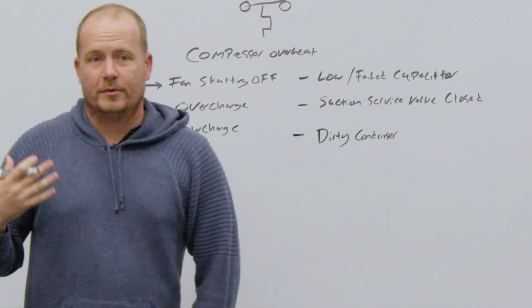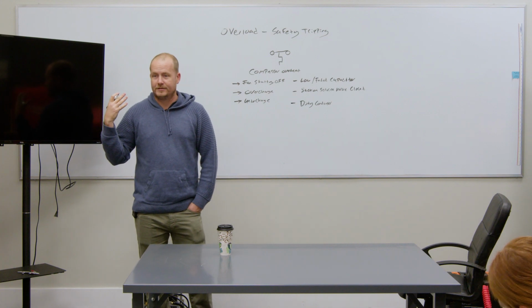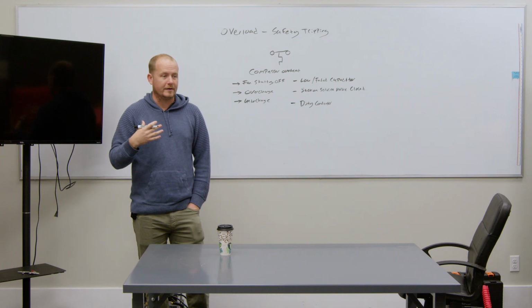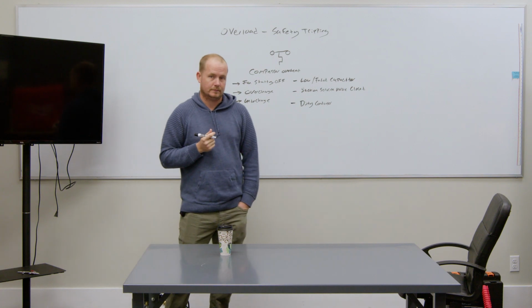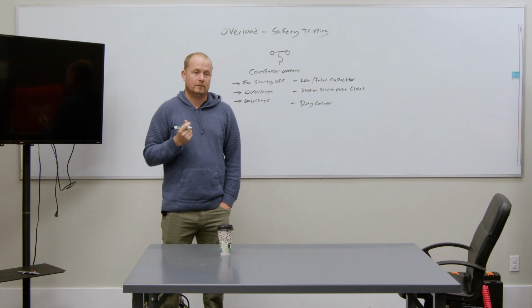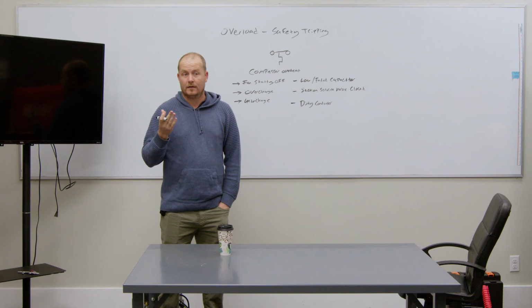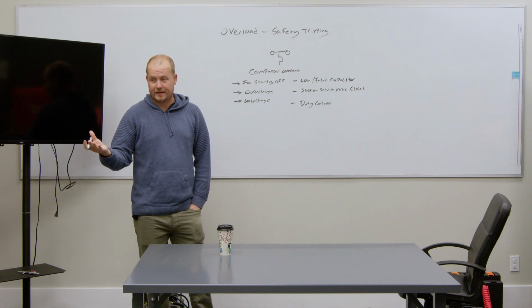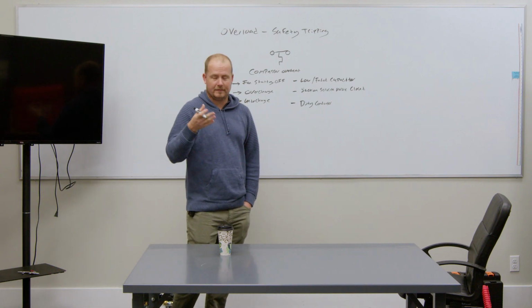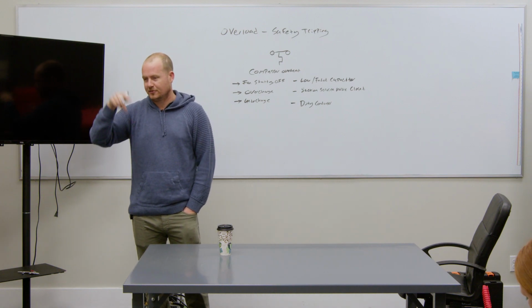So if you run into a compressor that is going out on thermal overload, what are you going to find? What is it going to be doing? Well, what will be off? Hold on, what will be off? The fan will be running, generally speaking, and the compressor will not be running, sorry, opposite. Twist it, turn it around, other way.